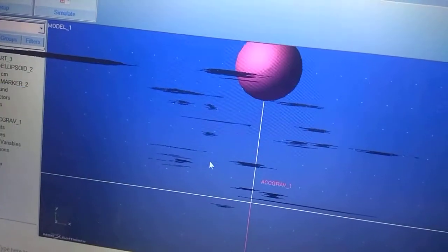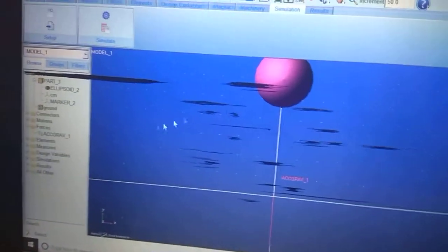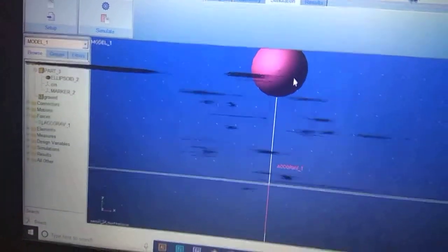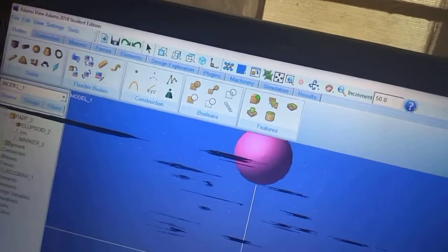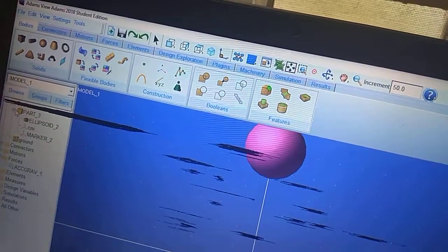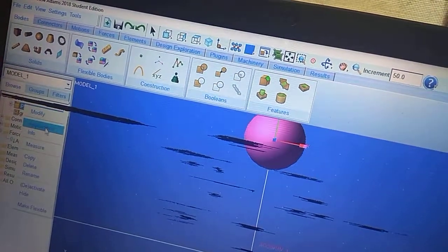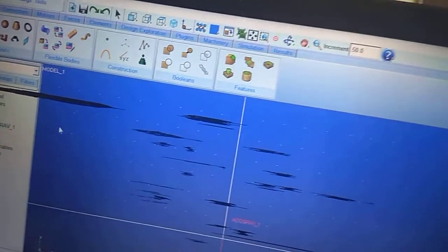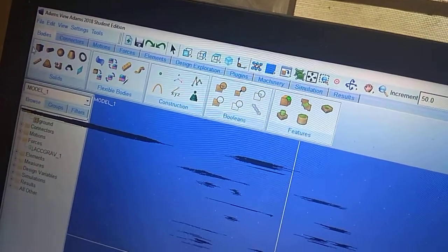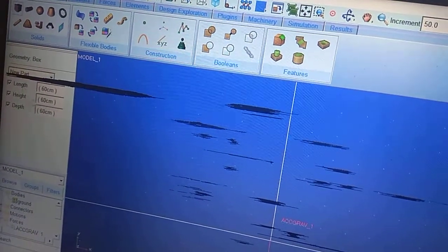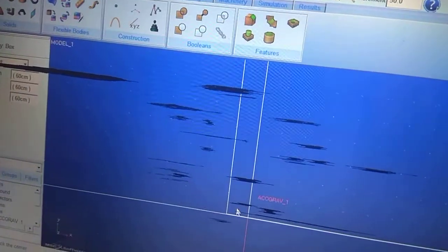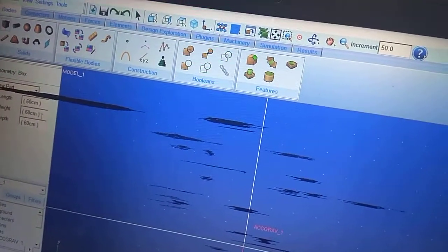I'm deleting this object. Now we just have this object. Now I'll explain. Okay, now it's better if you actually choose a square, because if I want to rotate this, you won't be able to see the rotation. Okay, now let's choose this cube. Now it's all actually preset 60, 60, 60 length, height and depth. So let's actually reduce the height. Let's try to make it like a plate. Let's make it 10.